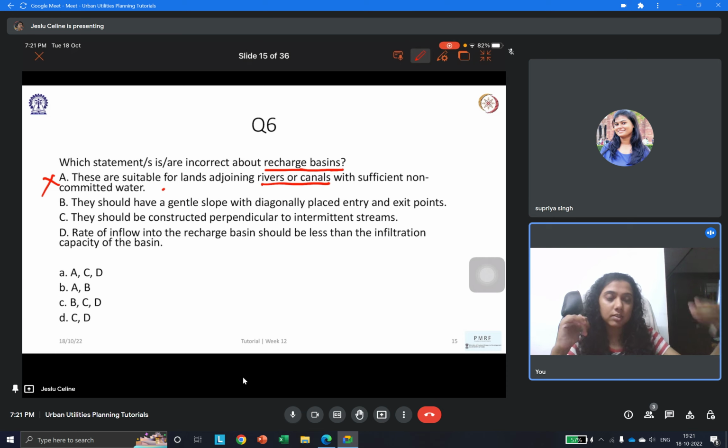Just because there is a water body nearby, the underground water level need not be as high, because if you have heavy draining, or a pump well from which we are constantly pumping out water, the water table can reduce. If the recharge is lower than the rate at which we are taking out water, the water level can go down. So that need not be true always, according to your logic.